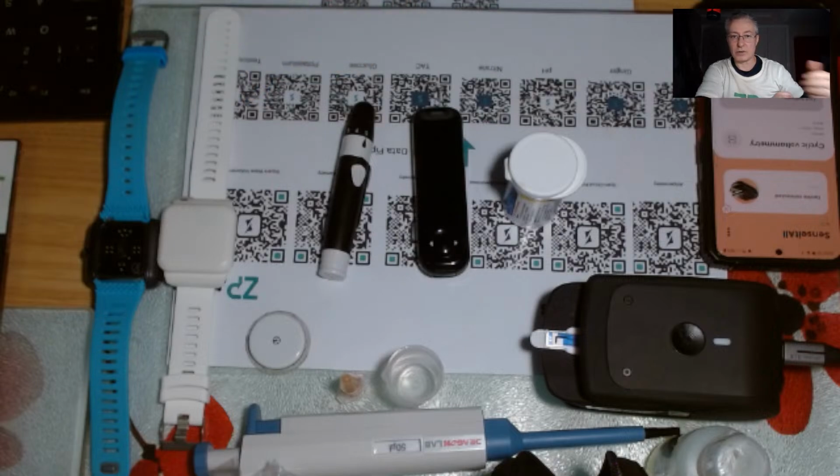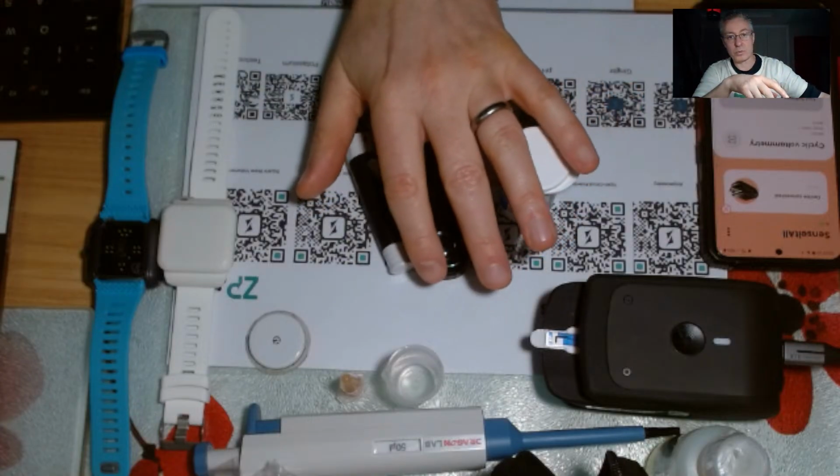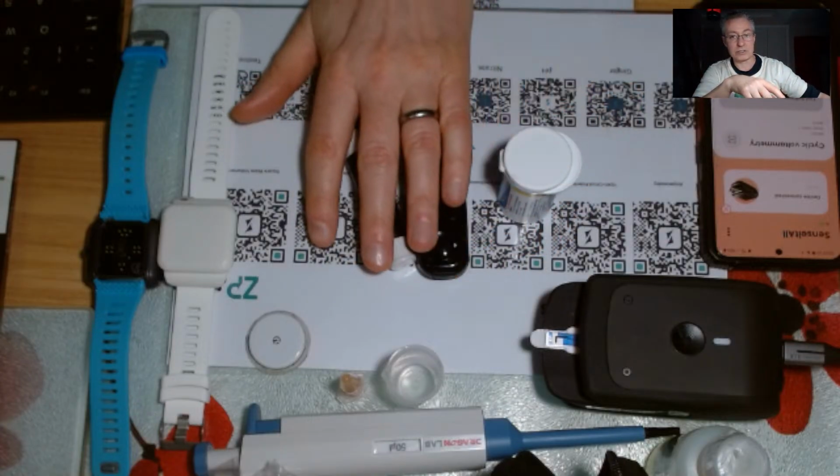Why is the glucose strip electrochemical? Why is it not fluorescence? Why is it not optical? I'll answer it now. It's because it's low cost, simple to do, and has no need for shielding from ambient light. It can work in really unprocessed samples like whole blood. I'll actually do a demonstration of this later down, in answer to one of the questions.